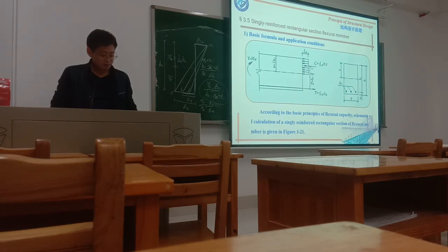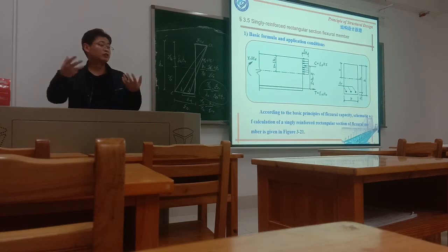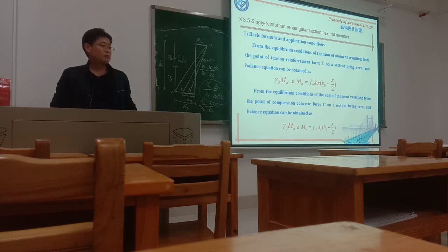Then, the moment induced by the external load is gamma 0 Md, and the resistive moment, the internal moment, of this section should be larger than this value. The resistance should be larger than the load.